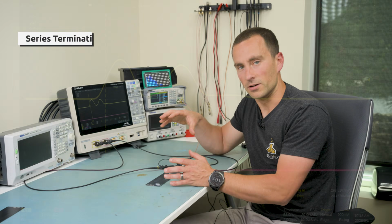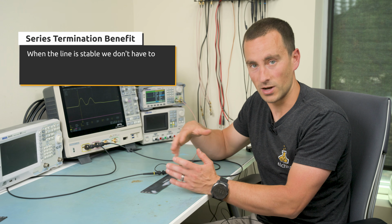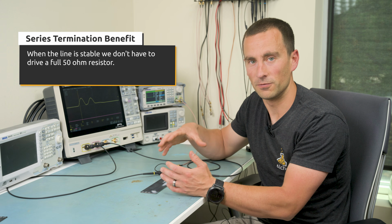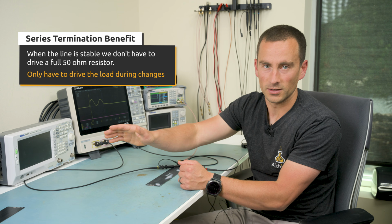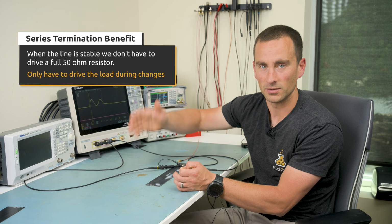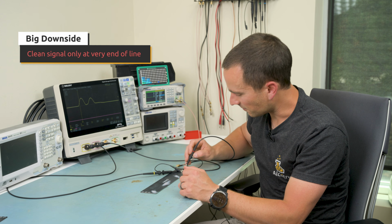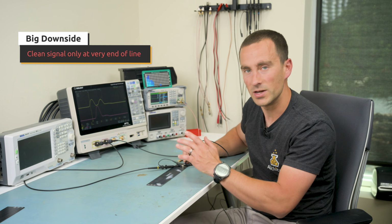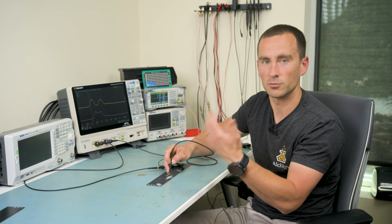So with series termination, we have the benefit that when the line is stable, not switching, we don't have to drive a full 50 ohm resistor. We only have to drive that initial load during the swing, during the upswing or the changing of the signal. The big downside is that you only get the clean signal at the very end of the line. Anywhere intermediate, and you end up with weird combinations of the pulse plus the reflection.